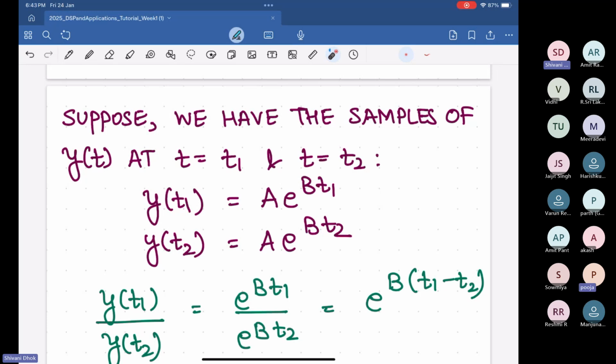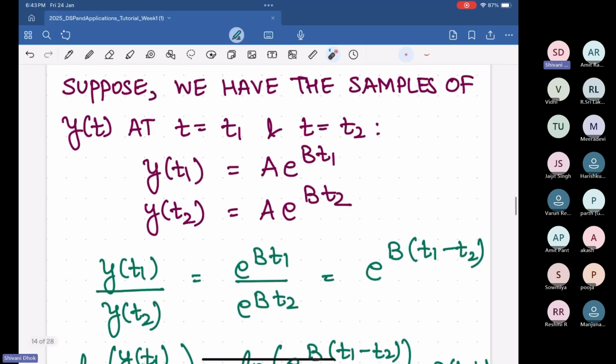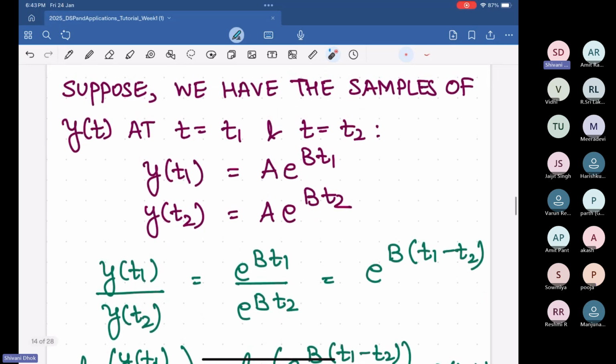Okay, ma'am. So this kind of question was there in last to last year's assignment, in which something similar was asked. Assuming the maximum frequency, people wrote the sampling frequency as the answer. However, since the nature of the signal was known, we just had to figure out how many unknowns are there and just figure out how to find those unknowns. So the number of equations that you need to find out those constant unknowns like A and B here was the answer. So this is something similar to what was there in the last year's assignment.